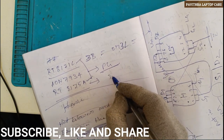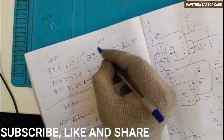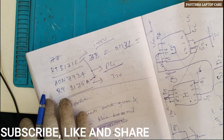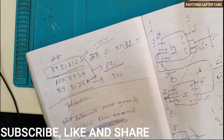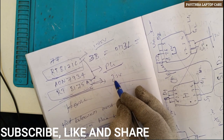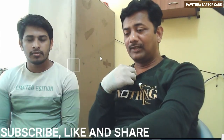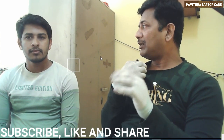One has 3.3 volts and the other one has 1.05 volts. This power good will mismatch here, okay? That is the reason I am telling you, if the IC has gone, you need to replace it with the same IC. Don't try with this IC. This one contains high-low MOSFET, but this one is dual MOSFET. You came to know what the fact is in the dual MOSFET case.